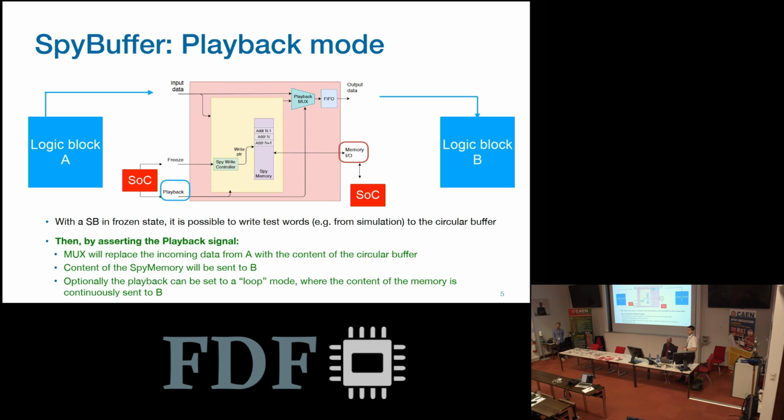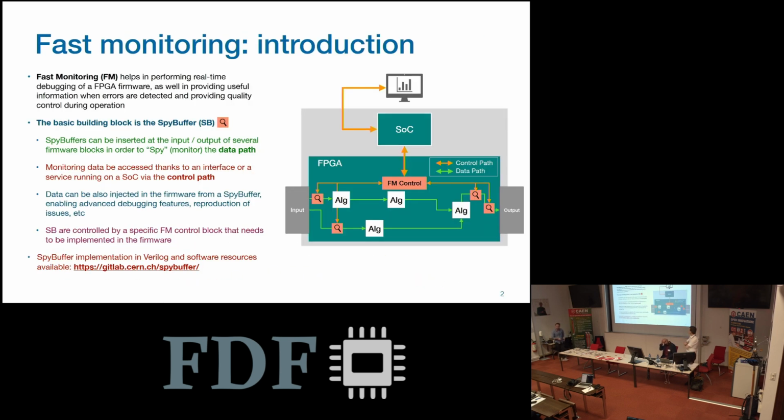Hi. Well, first of all, thank you for this amazing work. At my work, I have started to think about developing some real-time debugging system, and I think that you saved me maybe two weeks or more of hard work. So thanks. Only a little question. If I have understood well, you have to break the data path with these blocks between the master and slave. I have seen something related to monitor interfaces or monitor attributes. Are you using this, or is it possible to use this not to break the data path?